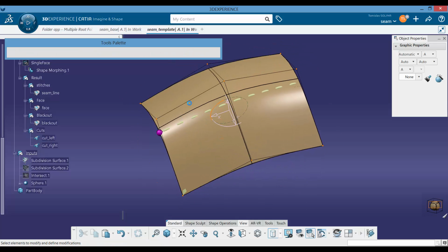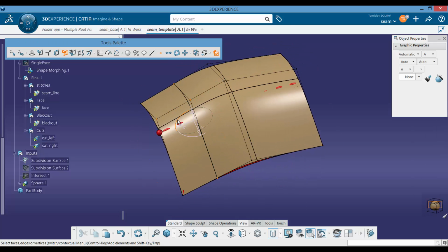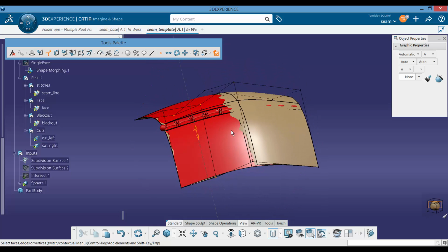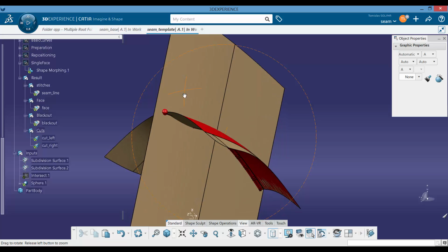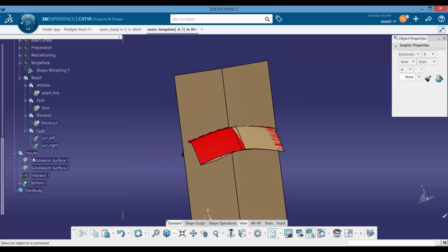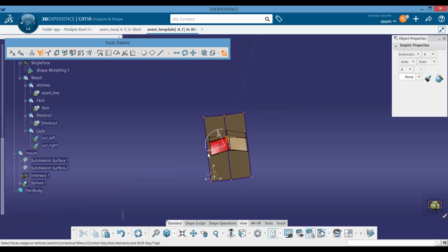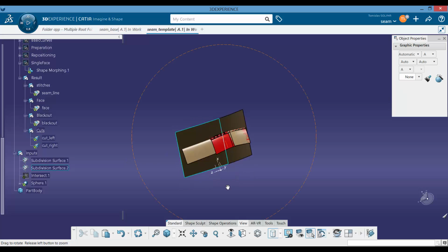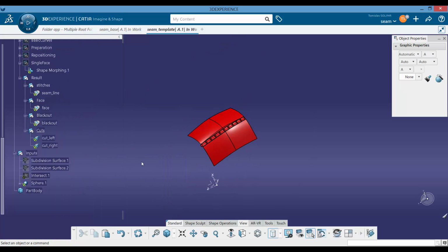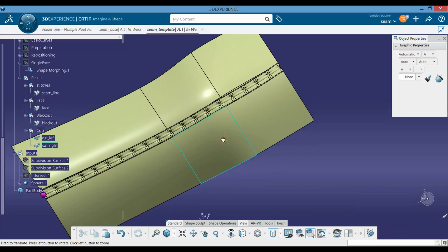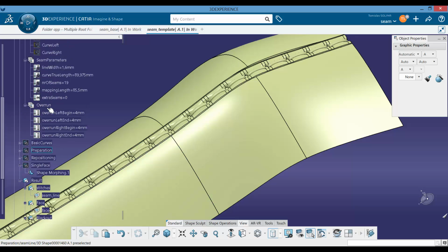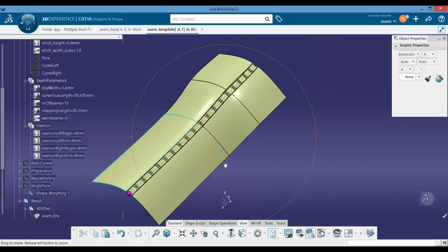As well, if we turn on back the shader with edges and add an additional span here into subdivision, cut, and let's move it a bit in normal so that we have really strange situation. So we have one surface, other surface, and now the transformation looks completely different. Even additionally, we can grab these two elements and extend them in some direction, doesn't matter, and we can hide those and make update. So as you can see, this will follow, and now instead of 10 elements we'll have 19 elements.